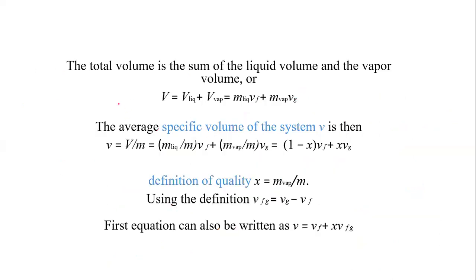So now here we have the equations that we use to perform the calculations. Most definitely, we're going to look at the calculations and the tables. We're going to look at the steam tables. So at this point in time, when you talk about the volume, it's simple because we're talking about two phases, which is liquid and the vapor. So when you want to determine the total volume of the whole system, you're going to say volume of the liquid plus volume of the vapor, right?